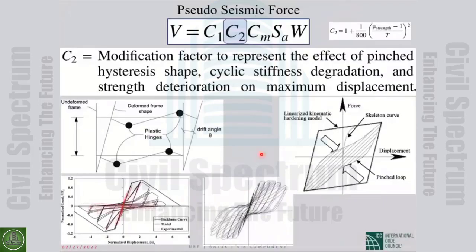Again, should we increase the elastic base shear to result in the same displacement for the building as in reality due to the other factors? Yes. One factor was that the period of the building is important, and the inelastic maximum displacement of buildings differs from the elastic one based on their period. But there are other aspects too.